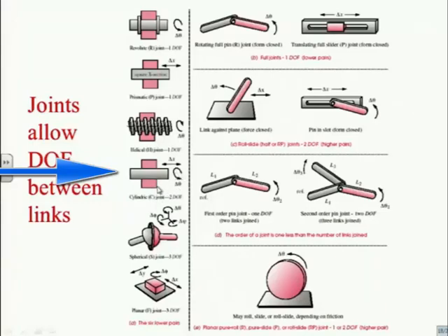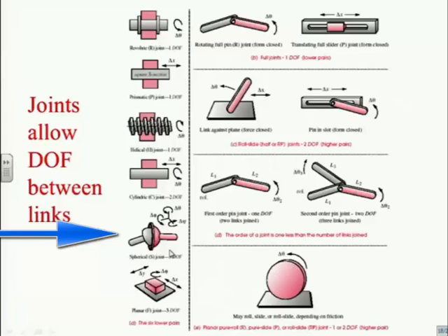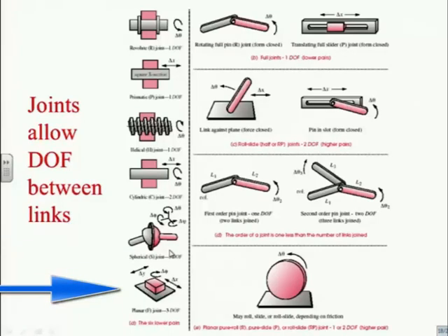That has two freedoms because I can both rotate it and slide it. If I want to get rid of the second freedom, I've got to put some constraints on the z direction so it doesn't move, or x, whichever you want to call it. So I can't move it left to right, but it only rotates. This is now called a revolute joint, and that's 1 degree of freedom. This spherical joint, or joystick, has 3 freedoms, all of which are angular. And the planar has 3 DOF. That's my book on the table. And I can move it in X, Y, or rotate.